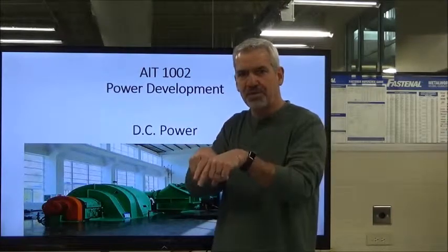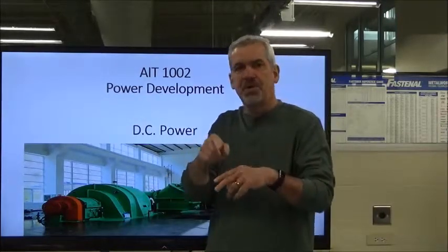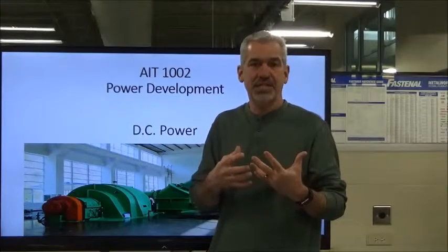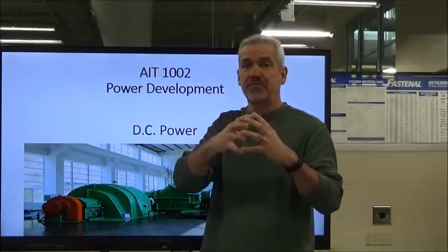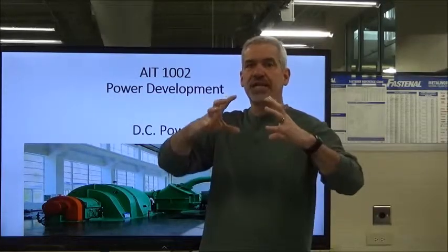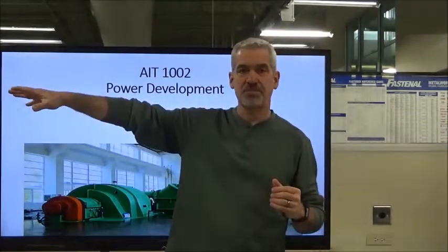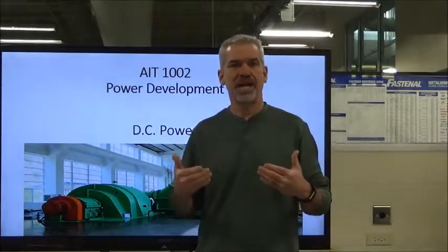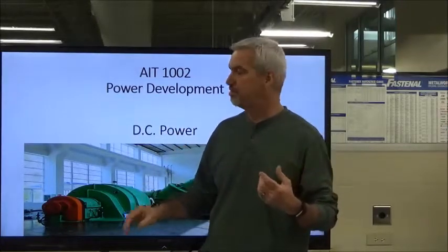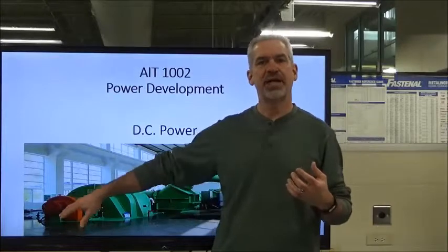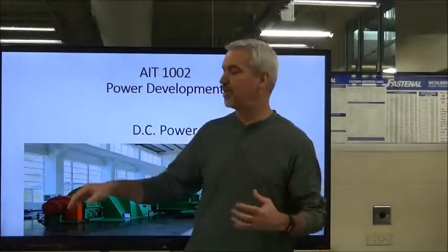We did this through carbon brushes, okay? And we transferred that DC voltage through the carbon brushes and into the spinning rotor. Remember, if we increased the amount of DC voltage on the rotor, it created a stronger spinning magnetic field. And that stronger spinning magnetic field resulted in a higher voltage coming out of the stator to provide us more power on our power grid, okay? So as the demand for power at the power plants increases, they in turn, it's not quite as simple as this, but they in turn increase the voltage going into that spinning rotor, and that creates a stronger magnetic field to help keep up with power demand, okay?